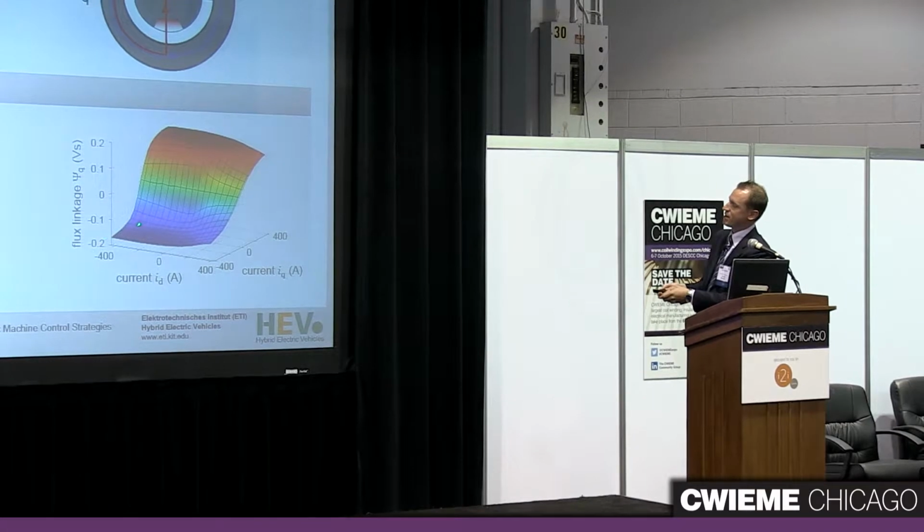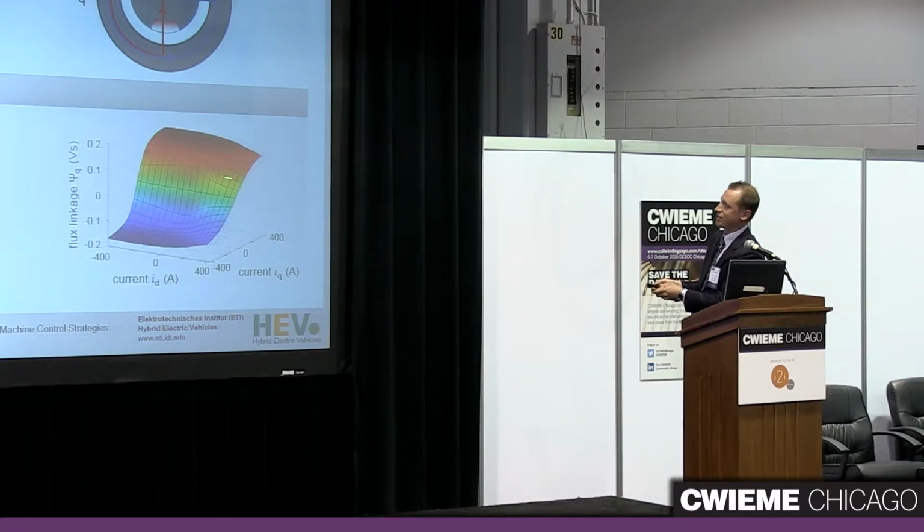Again, how can you model that? Let's keep it simple. You can just think of the flux linkages as two-dimensional functions of both current components. So the D flux linkage not only depends on the D current, but also on the Q current. That's it. This is exemplarily done here. This is an FEM calculation of such a motor. You see the Q flux linkage, and you can clearly see the saturation effect right at the back here, and that the plot gets distorted with changing D current, and this is due to the effect of cross-coupling.